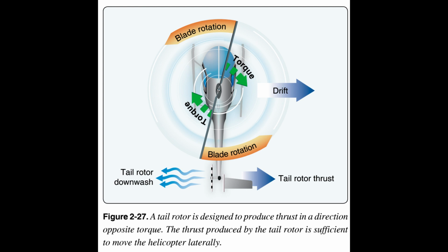3. The helicopter fuselage will also be tilted when the tail rotor is below the main rotor disc and supplying anti-torque thrust. The fuselage tilt is caused by the imperfect balance of the tail rotor thrust against the main rotor torque in the same plane. The helicopter tilts due to two separate forces: the main rotor disc tilt to neutralize the translating tendency and the lower tail rotor thrust below the plane of the torque action.